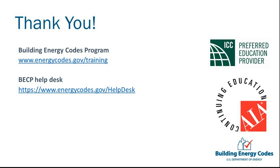I believe in Appendix G, you can trade off somewhat tighter envelopes. Let me get back to that, because I think you would know this, Mike, though, right? You can trade off? I do. If you're using Appendix G, and for example, if you're designing a passive house building, you can claim credit for building your building envelope tighter than what's required by the standard. So you could get credit for that and use it as a trade-off against some other feature, like more glass or something like that. So that is an option that is available.